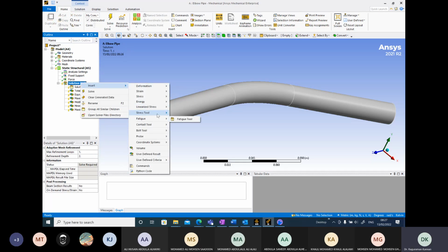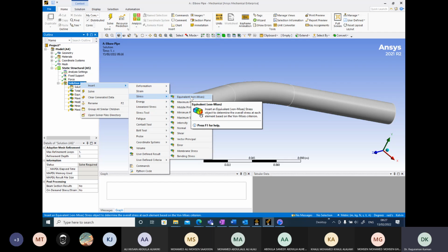And let's further see linearized stresses. What does this mean? The stress which is plotted here is the total stress. When your component is deformed beyond the plastic limit or yield limit, then you will have two components of stress. One will be the elastic stress, due to elastic deformation, and another one the plastic stress.